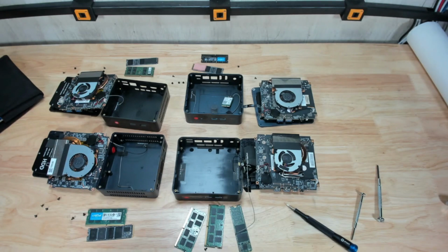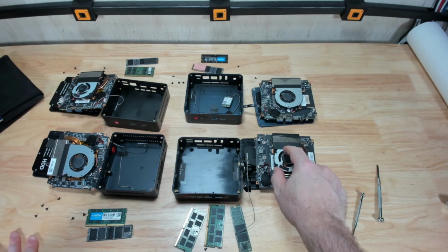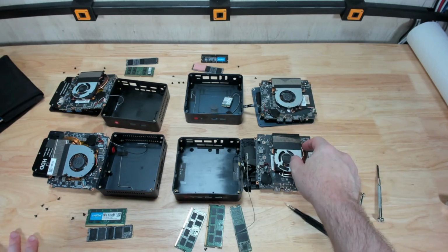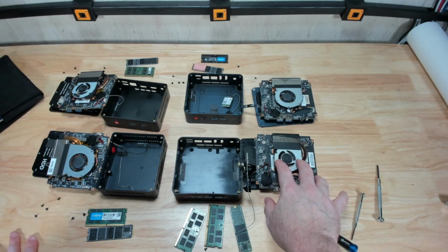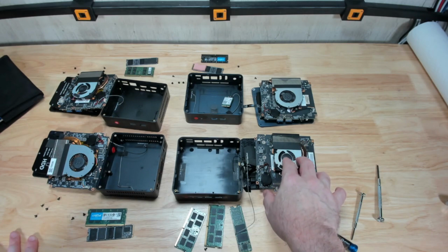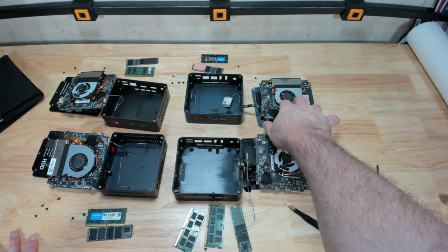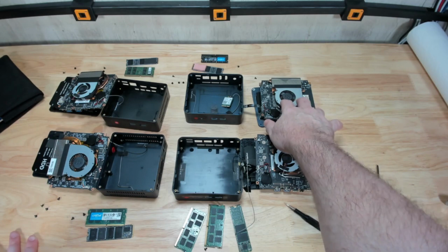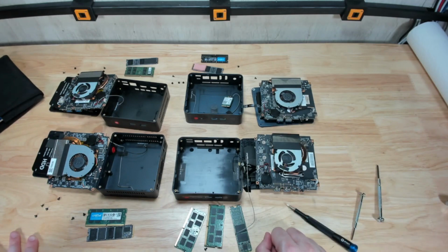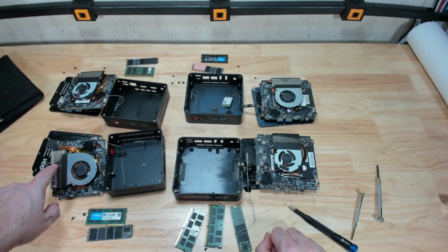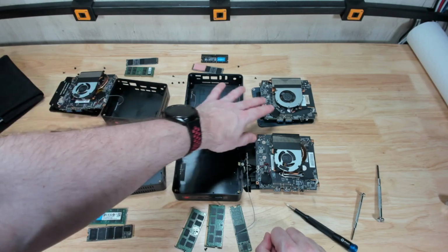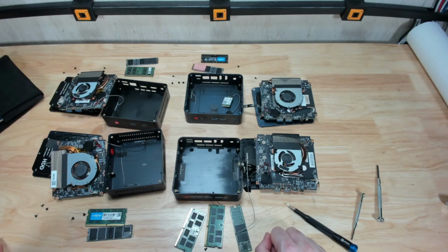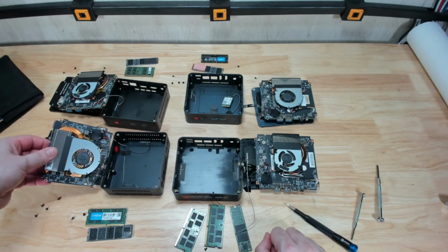All right, so if you take a look here, obviously your thermal solutions are a little different. This guy looks a little bit smaller than this guy, but this is the Celeron N5105, although it does have a higher TDP. Despite that, this only runs at about 20 watts, whereas this can run at, I think I saw somewhere from 25 to 30 watts actually, despite the TDP rating. And this N95 over here has a significantly thicker heat sink than the N100s over here. So, although it looks like a pretty beefy solution, you can see the nice thermal pipes here.